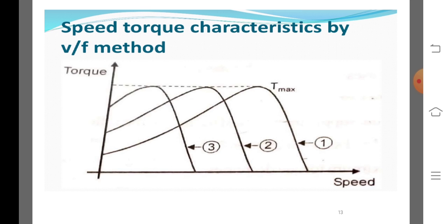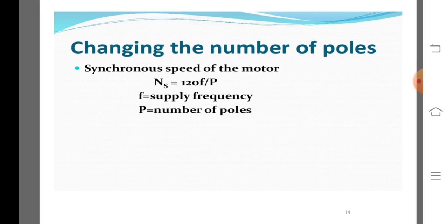We can notice from the equation that at the rated voltage and rated frequency, the flux is the rated value. If the voltage is maintained fixed at its rated value while the frequency is reduced below its rated value, the flux increases. At low frequency, the reactance decreases and the motor current may be too high. This type of frequency control is not normally used.